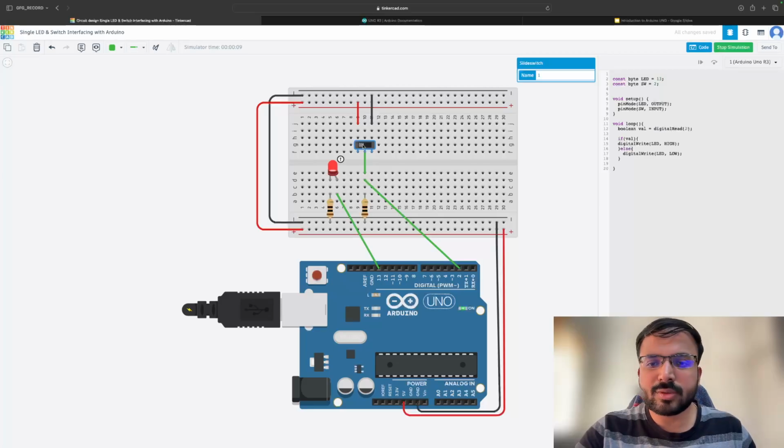So there are two types of switches, push buttons and slide switches, which we saw, right? So in general, on your hardware also, you will get these types of switches, physical hardware, and you can connect it in the same way, right? There is hardly any difference you will feel, right, when you actually apply this on a physical Arduino and take all these physical components in real time, right? So this is the circuit, and I hope you understood the point. And basically the difference was in the connections of the push button and the slide switch, how they were connected because of the different number of poles. Otherwise the code remains the same, right? You read from the switch and drive the LED output pin, right? So that is how it is.